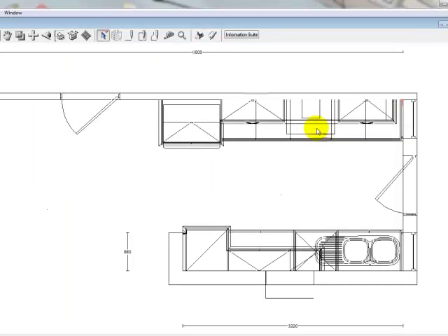If we go to plan view, we can measure from our point of the start of the wall to where our tiling would start, which is 1602 and 1800. So we know that our offset for the starting point of that tile would be an additional 200 millimeters.